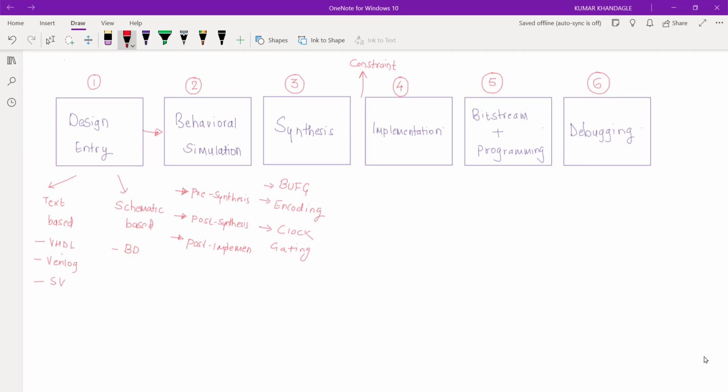Once that is done, we will proceed to implementation. This will automatically do the placement. As soon as we specify a constraint, Vivado will automatically choose the most suitable site depending on the pins that we specify. Here we could also adopt some strategies if your design requires certain specific constraints.